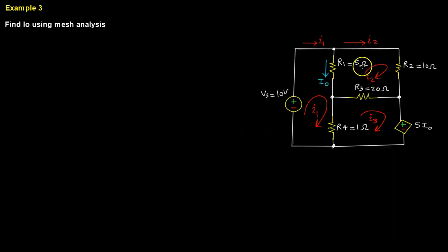So looking at this problem, before writing the equations, we're going to assign polarities. For R1, I'm just going to assign a common sense polarity, so I'm going to have plus here. For R3, I'm going to say any direction is fine as long as it's consistent. Let's put the plus there, put the plus there, now put the minuses in these locations. We just have to make sure we're consistent. Nothing here is breaking any rules for the system. So having done that, let's actually solve for the first mesh.